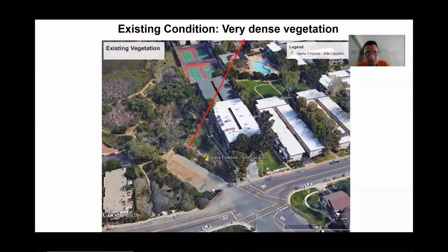Okay, let's continue detailing our model. What we have so far is a HEC-RAS model that has 8 cross sections, and those are getting data automatically from the terrain that we created. So that's good, and we can run it now. We can detail it a little bit.